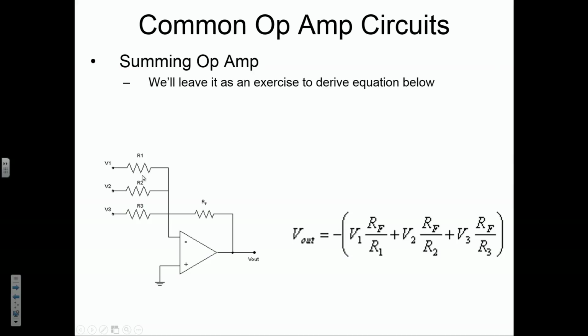But commonly we may, for example, be taking a measurement of temperature on a surface, and we don't think that taking temperature at one spot on that surface gives a good representation of what the temperature of the whole object is. So we put out 3 temperature transducers, and we make R1, R2, and R3 equivalent. And so in that case, we're taking an average of those three temperature values, and we're getting an average temperature out. This would be an average voltage from each one of the transducers.